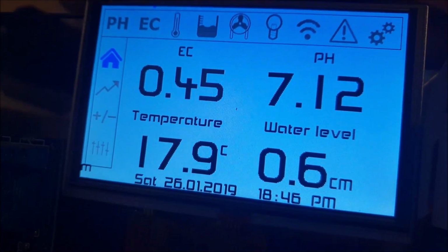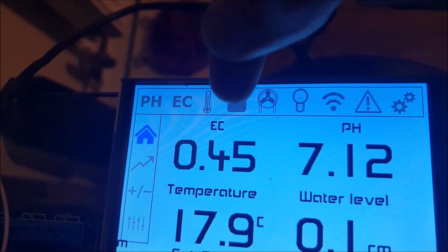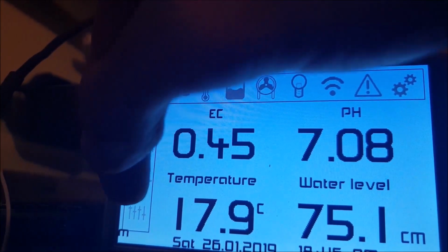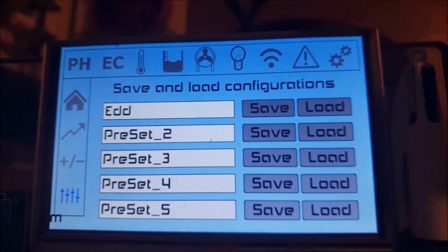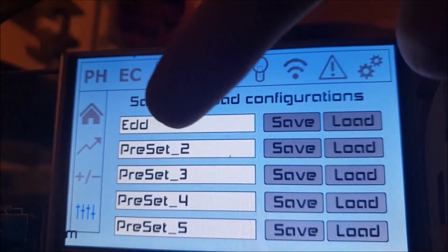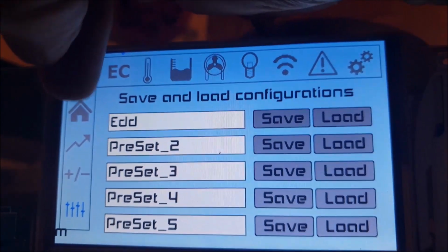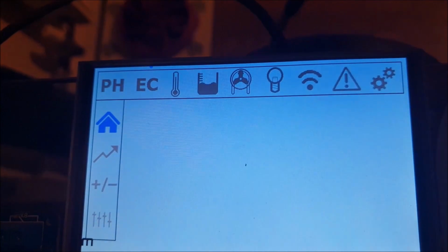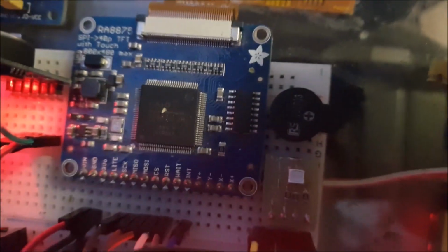So that's why it has to send this over SPI to this, where it then buffers everything in the memory, and then I can get the luxury of just saying, well, let's just update this one little pixel once you've displayed the page. As you've seen, what's a slow page to load? The menus. As you can see, it's loading it bit by bit. But once it's loaded, all it has to do is just refresh whatever I'm doing. So I call that the initial commit time. The initial commit time can be quite slow, but then once you're in the page, blazingly fast. So thank God it's memory addressable. And that's the display covered.